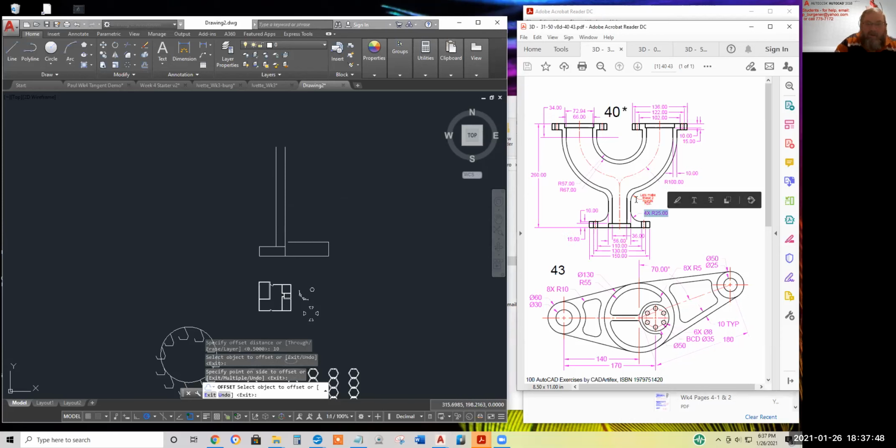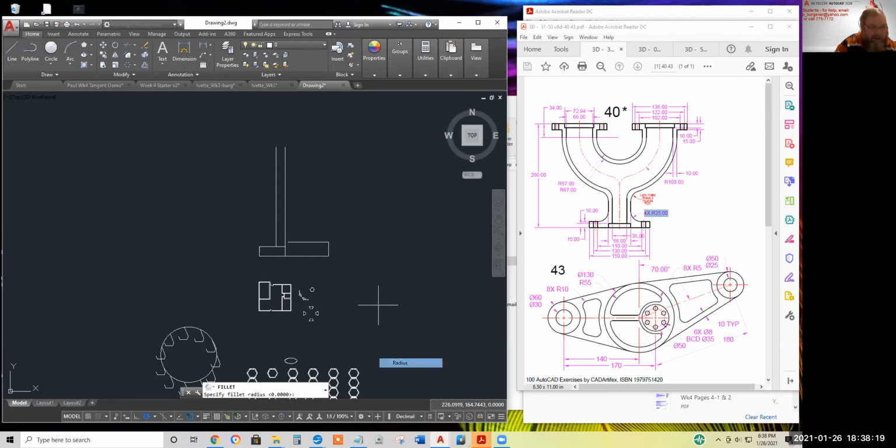And all 4 of these arcs here, this is where the typo is in your book. Your book has this at a much higher radius. It says, I think, 6 radii or 25 units. I only see 4 that size. 1, 2, 3. Anyway, where was I? Let's fillet it by 25. I don't think I'm going to get to do both of them. Right click, change the radius to 25, hit enter, click, click.